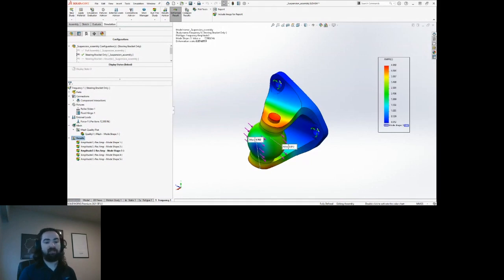This more complex static study will take much longer to run, but it should produce more accurate results. Once it's finished, we can compare the results to the first simplified static study, and based on how close the results are, we can decide whether the results of all of the studies we ran are valid or not.